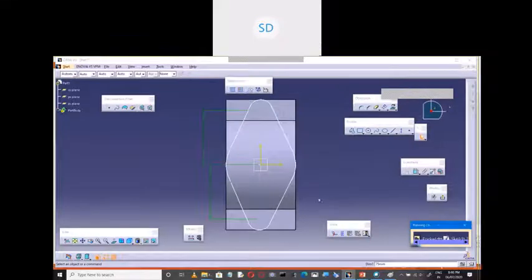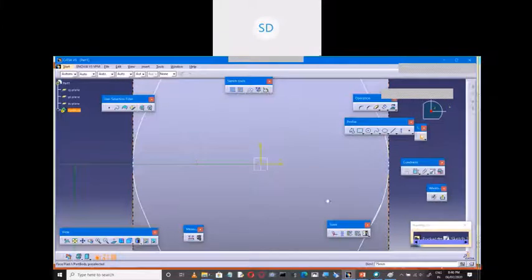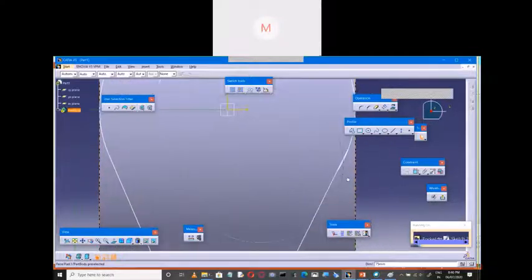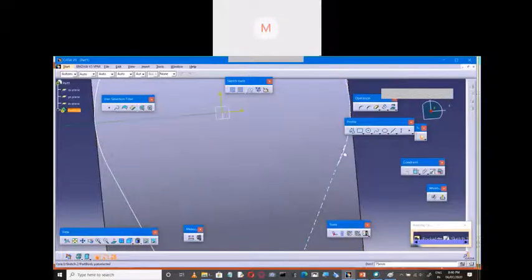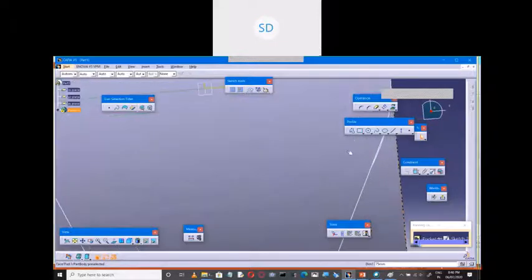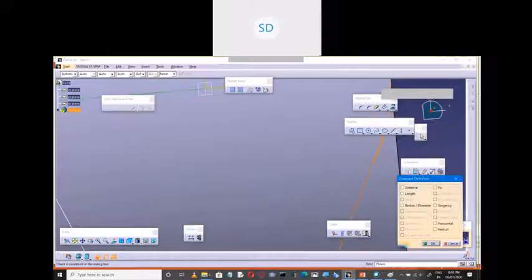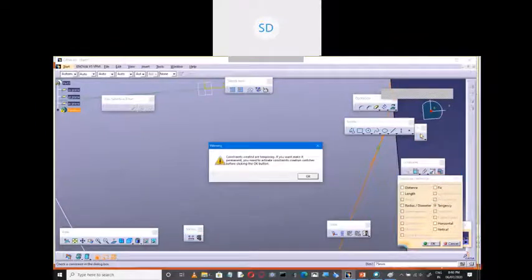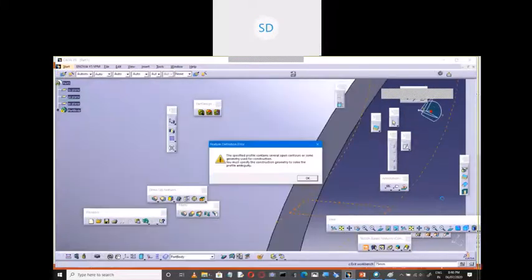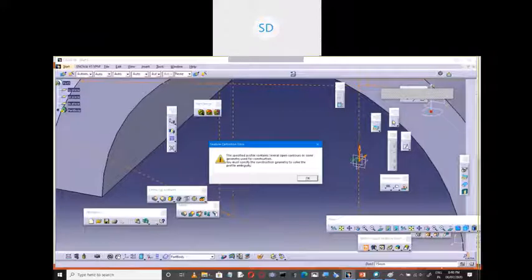Now I'll go for editing the sketch. In this case, you go for clear zoom. Again, let's look out here. This is not in a tangent portion. Now you select this line as well as this arc, then go for options here and make it a tangency. Then use trim and remove this extra portion. Now exit. Say OK.